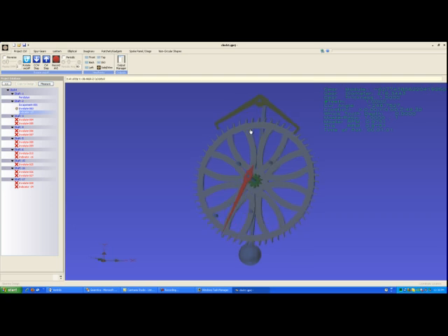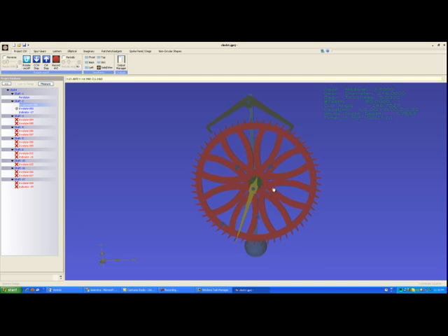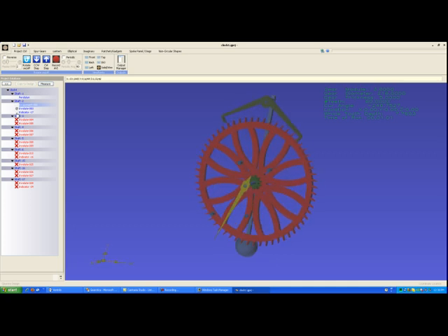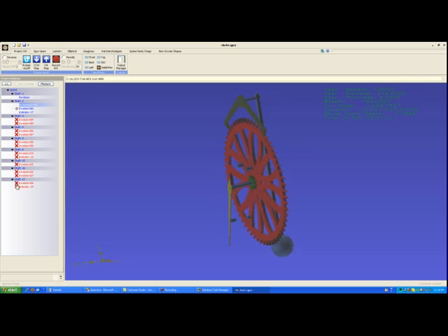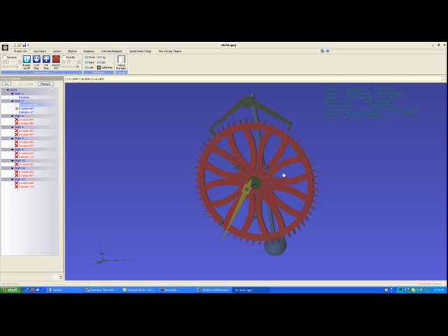First, I added a pinion, a 10 tooth. It's recommended at all times when you use spur gears that you use at least 10 to 12 teeth. I like 10 because it's a nice divisive number. I can figure stuff out in my head much quicker. So if you picture the way that this would work, the deadbeat and the pinion will be glued together or bonded together in one way. They could be both bonded to the shaft, or they could be loose on the shaft, yet bonded together as gears. But you have to picture that basically those two will always turn at the same time. So our small pinion is now turning at 1 rotation per minute, just like the second hand.